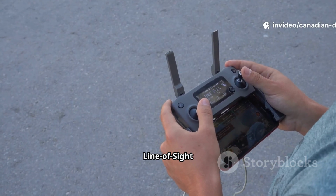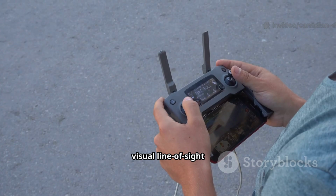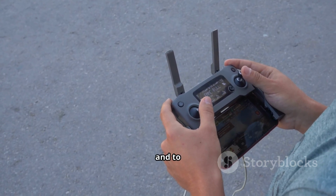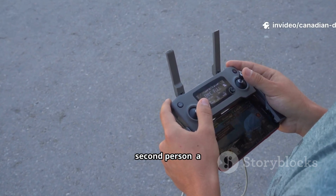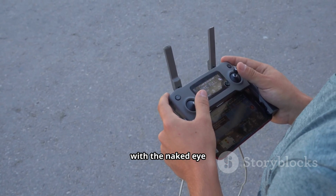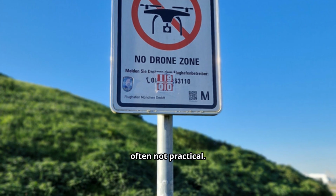C. Visual line of sight, VLOS. You must always keep your drone within unaided visual line of sight, no binoculars. You must be able to see its orientation, position, and to see and avoid obstacles and other aircraft. Using FPV goggles: you can use them, but you must have a second person, a visual observer, beside you maintaining VLOS with the naked eye and communicating with you. For basic ops, this is complex and often not practical.